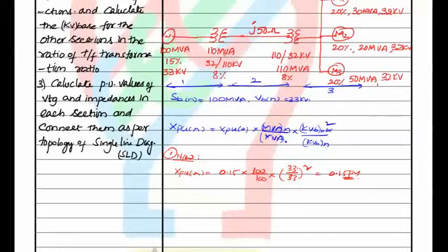So we'll choose the second network. When we are going from here to here, there is a voltage change: the voltage changes from 32 to 110 kV. This is the major reason for doing a lot of calculations in absolute units, so in order to avoid that, we will choose the per unit system. How are we going to do the calculations? By choosing the base values. The formula we are going to use is V2 base divided by V1 base is equal to the transformation ratio K, which is nothing but V2 by V1.